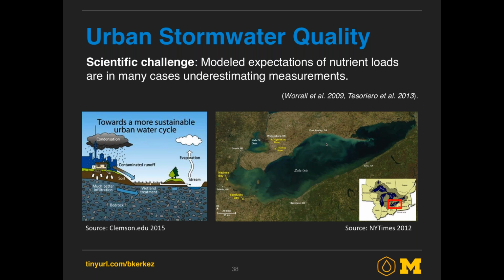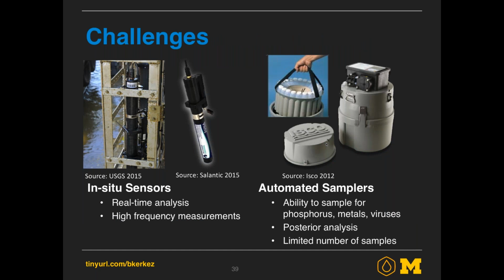And when it comes to measuring water quality, we're not at a place yet where we have reliable sensors for a lot of the stuff that we care about. So in an ideal world, we would have continuous measurements for all sorts of parameters that we care about. But the fact is, for a lot of things like nutrients and emerging contaminants, we just don't have good sensors. So we can't just stick something in the water and get minute-scale or second-scale resolution. We actually still have to rely on the things that were shown last week during the seminar, which were these samplers.